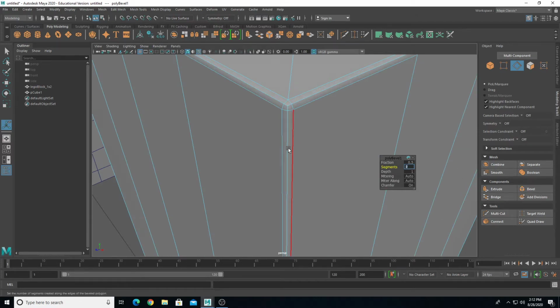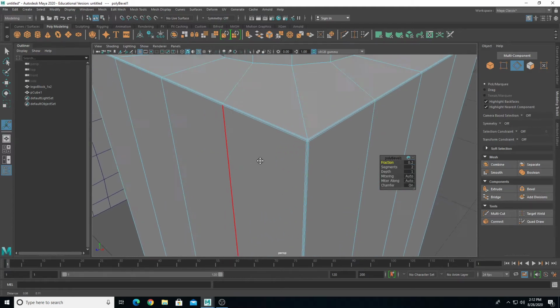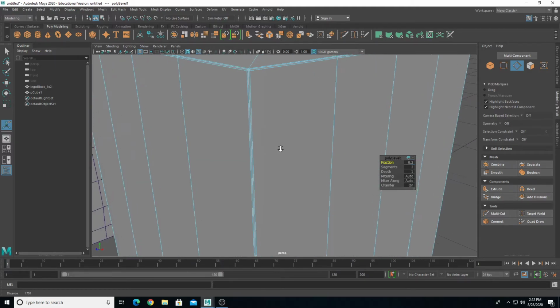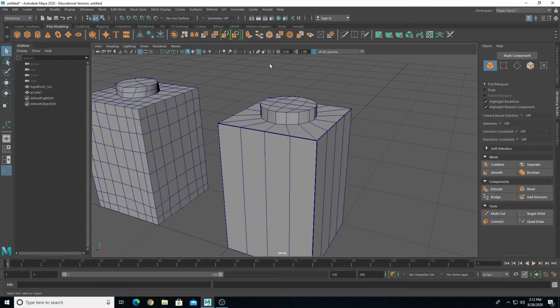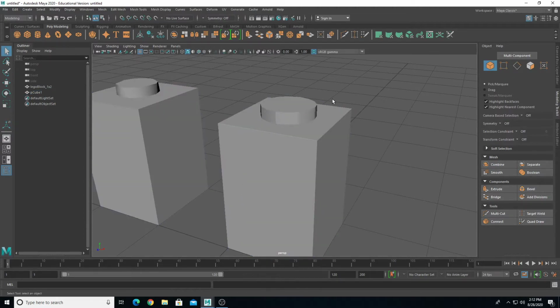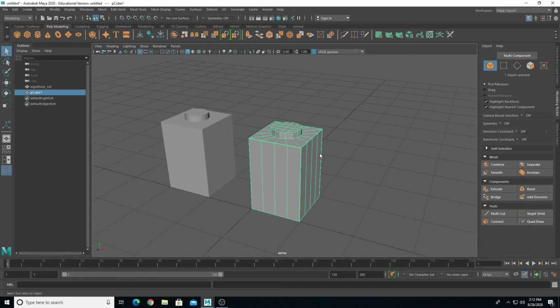We just need 2 for right now because it's going to be a small bevel. You can change the fraction to something much larger, 1.5, something much smaller, 0.2. I think 0.2 is pretty good. Gets the rounded corner that we want without being too crazy. So we can turn off our wireframe and see what that looks like when we start to duplicate that. So beveling's really nice for creating more natural looking edges that are machined or man-made.